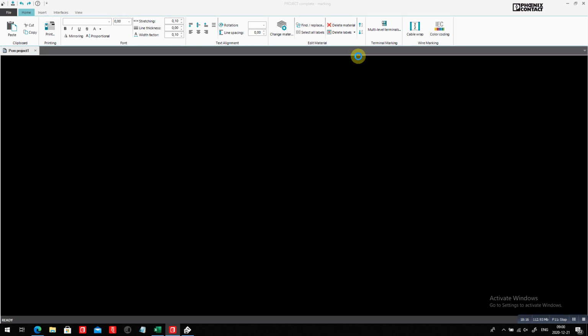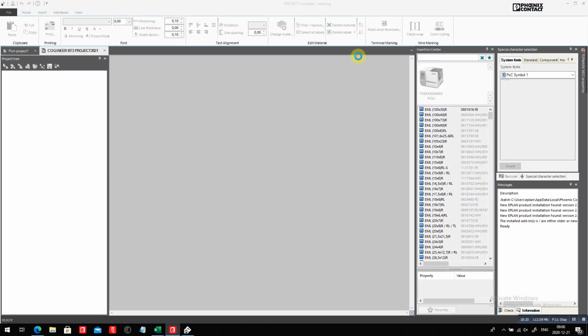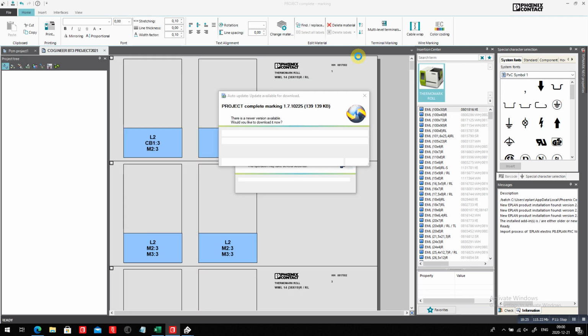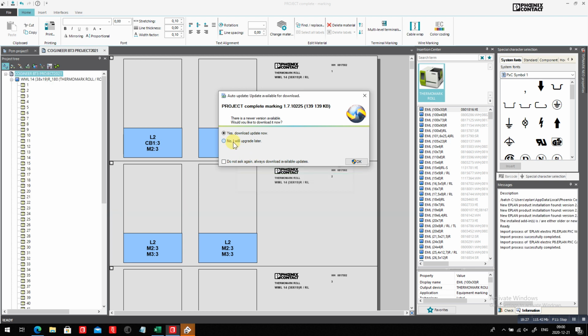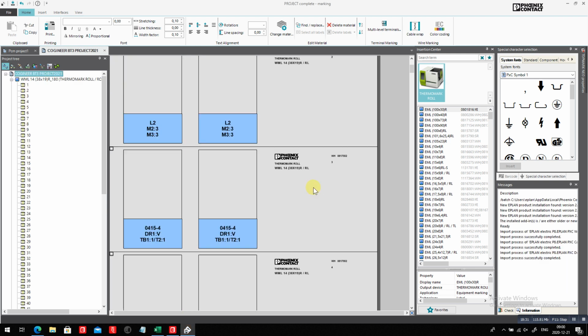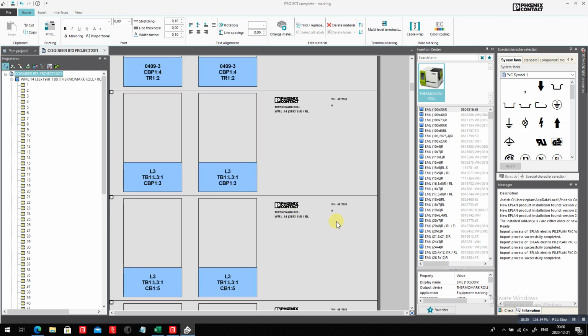So if you're wondering where the labels come from, well, here they are. Let me just not update this. Here are the labels. All labels are pre-printed. So I can now have this label put on the right wire. If you sort these two lists exactly the same way, you can use the wire station. This will probably cut a quarter of your production time in your panel.